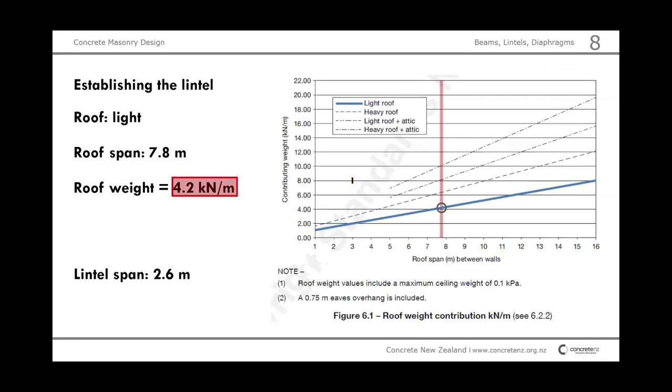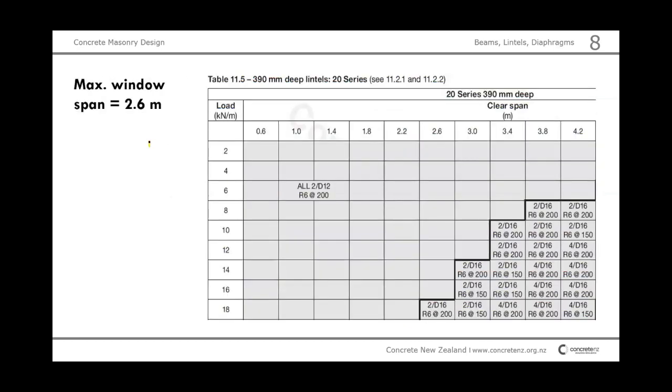And we have to now also quickly look at the design. The maximum lintel span, I'll just tell you now, I'm the architect, 2.60 meters. This is the door to the deck, the door to the terrace. There's a sliding door, huge door. 2.60 meters, that's the maximum span for the lintel of our building. And once we know that, we go into table 11.5.